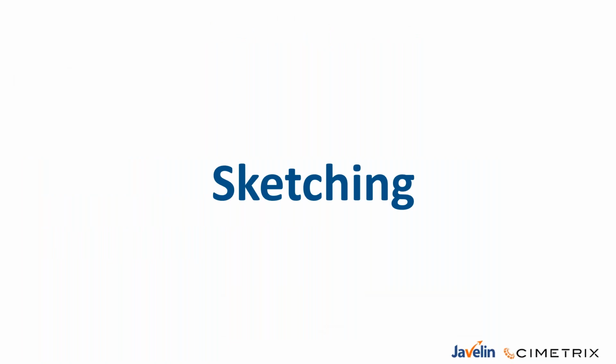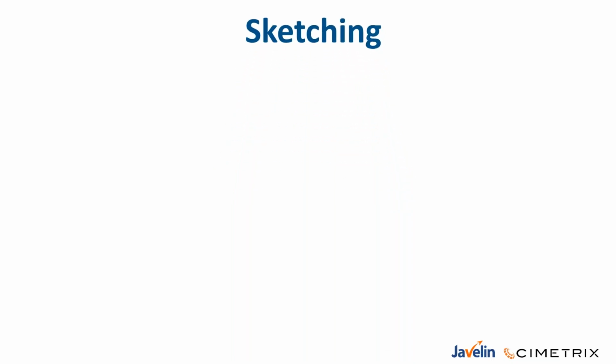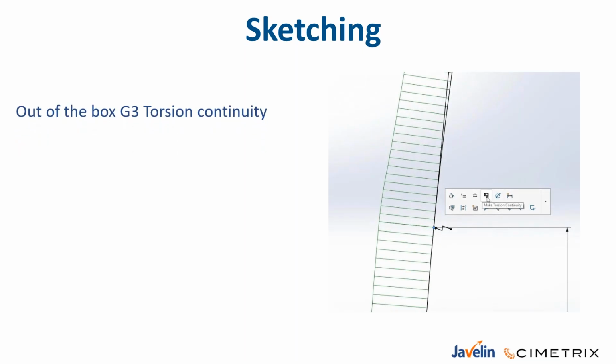Okay, let's move on to sketching. Everything in SOLIDWORKS typically starts with a sketch, so it's a pretty critical part of the workflow. And a couple of enhancements that Colin and Claudia talked about during their parts and assemblies webinar a couple weeks ago was the G3 torsion continuity. So I just wanted to review that here. Before, we did not have G3 continuity. We could kind of fake it when we were sketching with a couple workarounds. But now in SOLIDWORKS, out of the box, it's on the quick access, the in context toolbar. You've got that G3 continuity to give yourself some really nice curvature transitions when you're working.